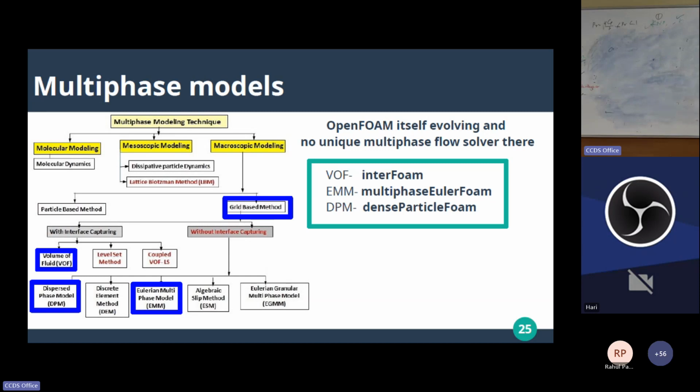All the time I'm going to use Eulerian, but when it comes to multi-phase, locally these gaseous pockets are isolated, like when we are looking at a marine propeller. Most of the domain is liquid, but at some points you will have a gaseous phase. So they treat them as spherical, or maybe non-spherical, bubbles whose center of mass is located at one location. Let me advect it so that they can exchange heat, mass, even momentum across them. We will see that. So when we do that, we call it Eulerian liquid, Lagrangian gas, or Lagrangian particles. We'll see.